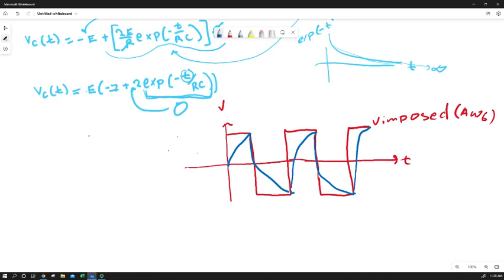So if I wanted to confirm what R and C were, or what the product is, I can use, I'm going to draw it in purple here, I can say, well, I know that V sub C at any time is going to be equal to whatever my amplitude is of my applied signal that I'm applying to the whole circuit, which I could set on my PicoScope and I will measure. Since this is going to go all the way flat, I will measure this. I won't trust what I applied because maybe I'll get some sag, but I'll measure what that maximum is.